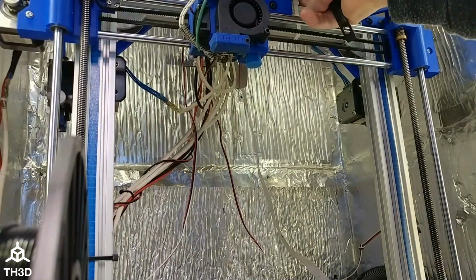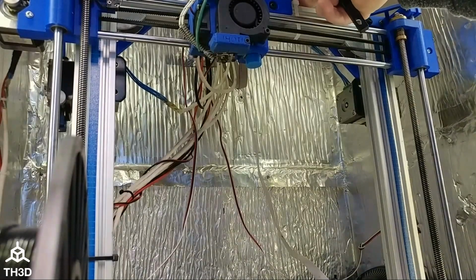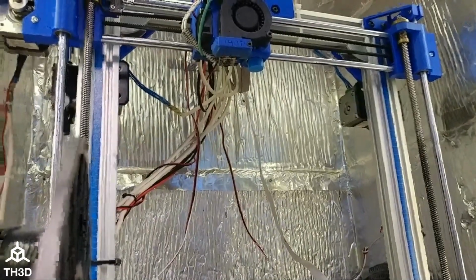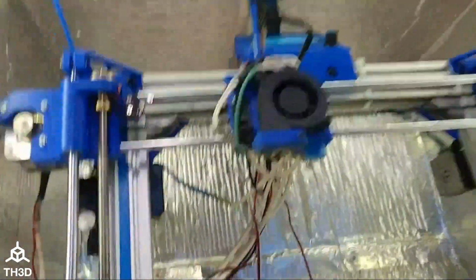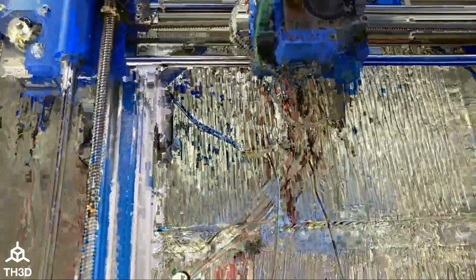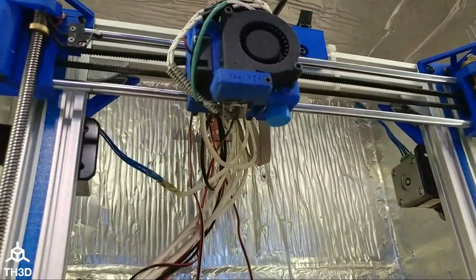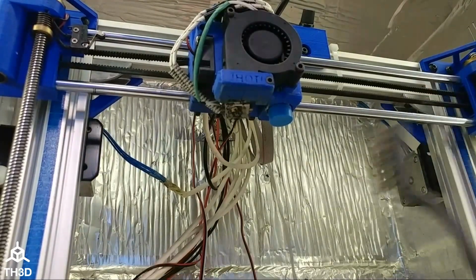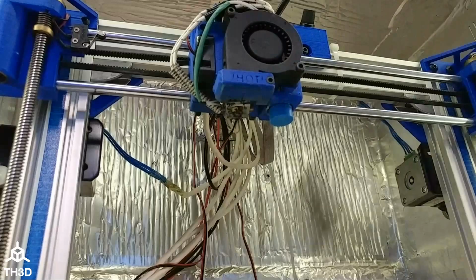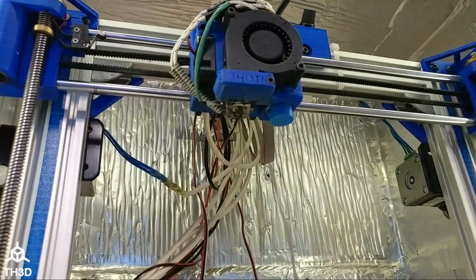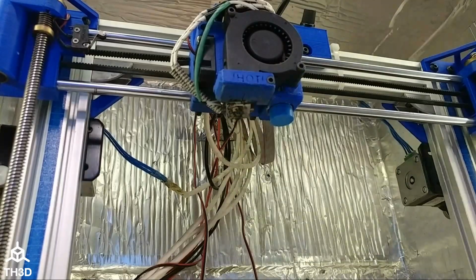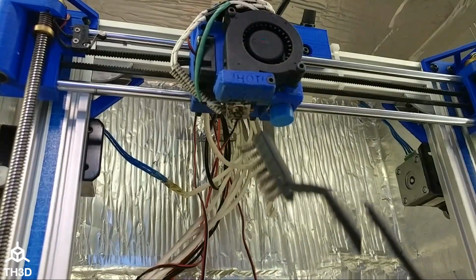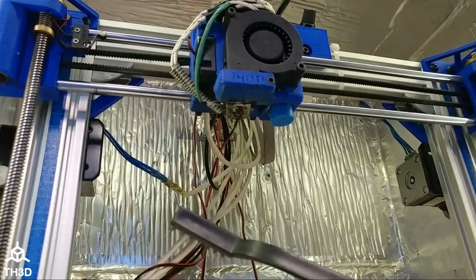Perfect. All right, so I'm gonna look at my thermals here. We're still at 240, so that's good. It hit the target temp, but we don't have anything going on. We don't got filament going through this. We don't have my layer fan on at all. We just have it heating, and it's maintaining temperature pretty good. It's fluctuating about 1 degree. So I'm going to clean this off, and then we're going to do a silicone sock on here, and then we're going to PID tune the hot end.